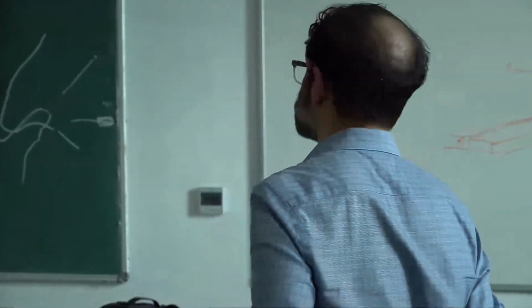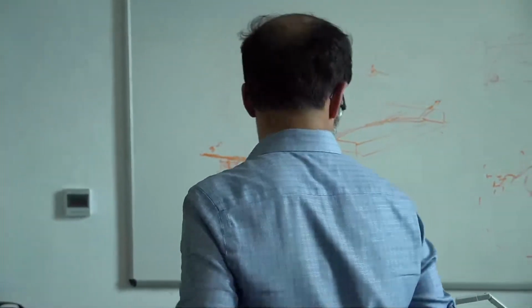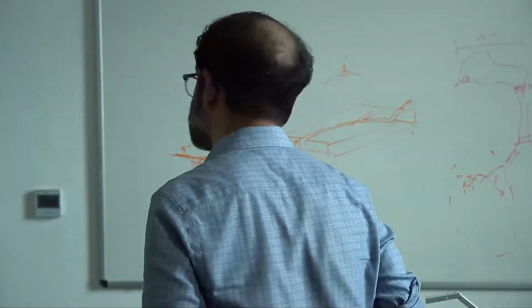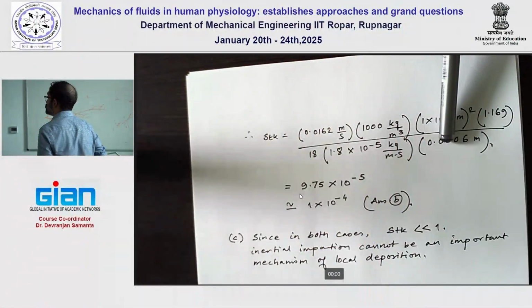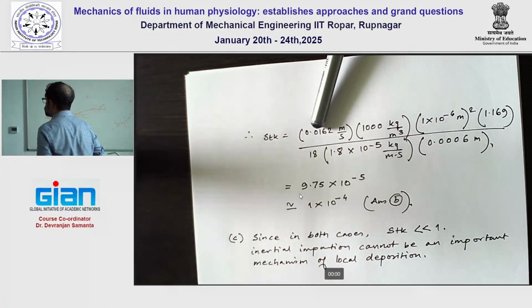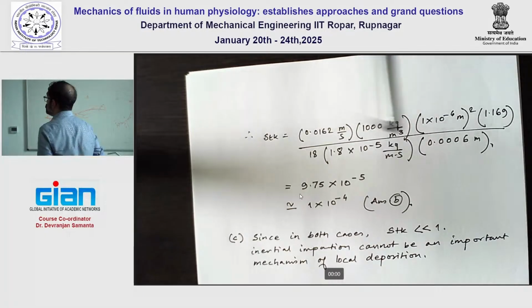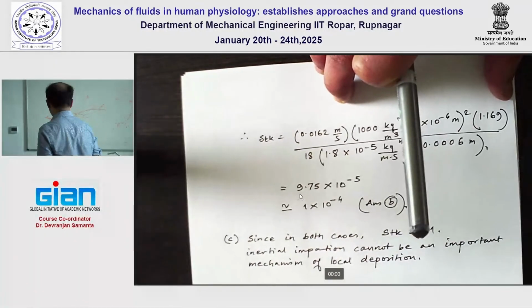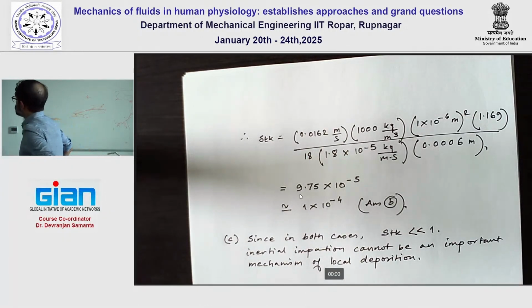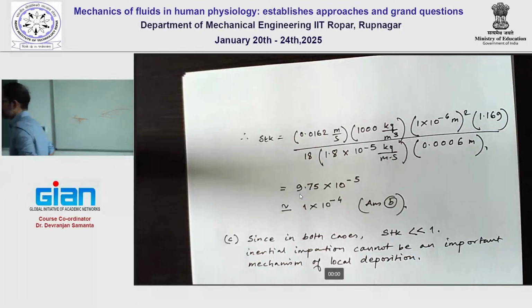So this is the Stokes number. This D, which is the channel diameter, is going to be small, 0.006. This flux is going to be small as well. So the only redeeming factor could be this particular term, 10 to the power of minus 6, which is what the small d was, the particle diameter, and it is helpful because it's a square term.